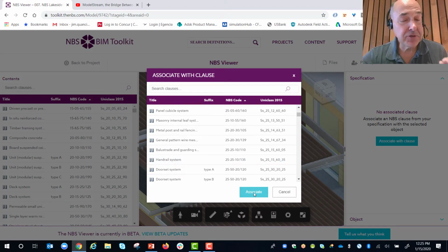The other thing I will say, for a lot of people, making these connections is not a manual thing. You actually start by running queries, and that's how most cost estimating integrations are done. You run a query: show me all the walls, and I want to connect those walls to my cost estimating system. Show me the walls of various types, and let me connect them to the various costing information I have in my cost estimating system.